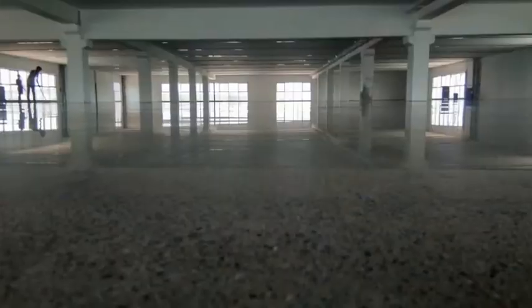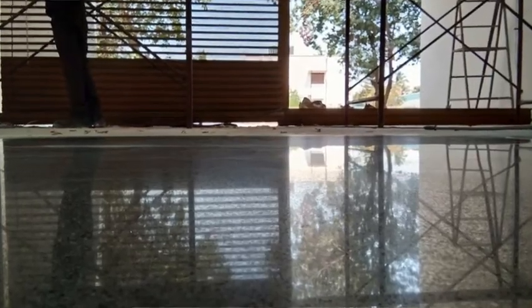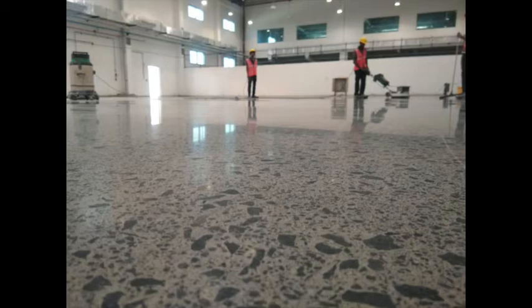So when you follow these 4 steps, there's no way your polished concrete can fail. Now, based on the final use case, whether it could be an automobile factory, an IT park, a supermarket, or a school, the extent of your grinds, the extent of gloss levels you want, and so the extent of mechanical polishing that you need can vary. And based on this, the cost can have an impact. But if anybody is promising you to not do these 4 steps, then that is not called polished concrete.